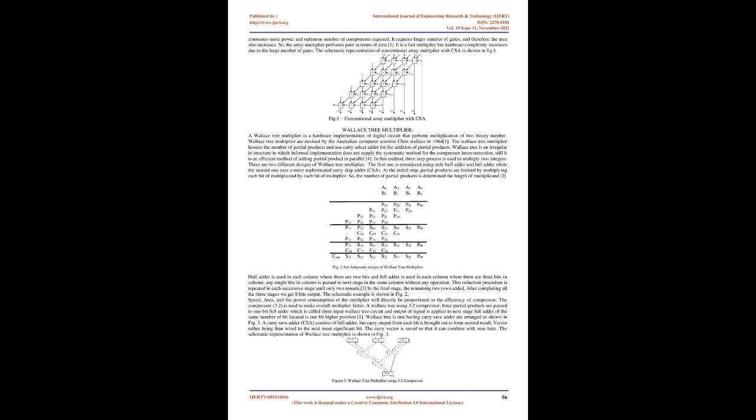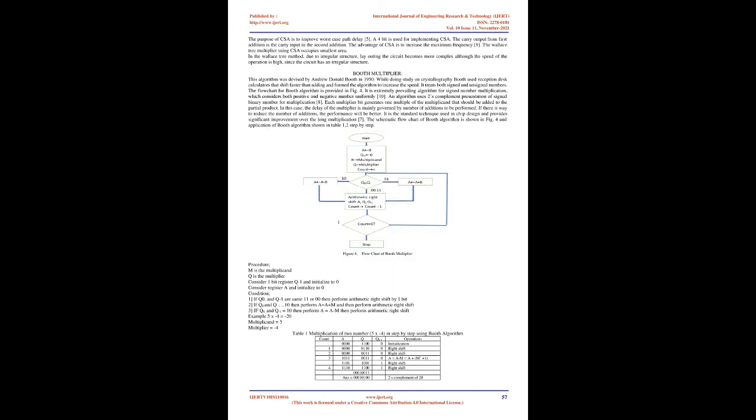Min C. Park et al., 1993, presented a new architecture using a dual array tree structure, which includes dual partial product arrays divided from one partial product plane of the conventional array multiplier.